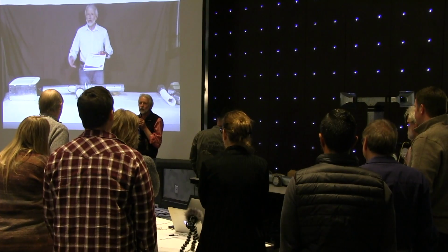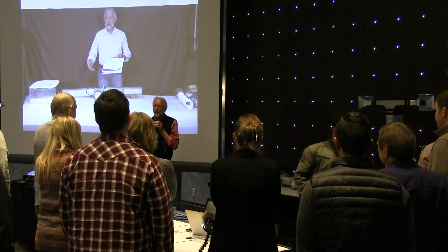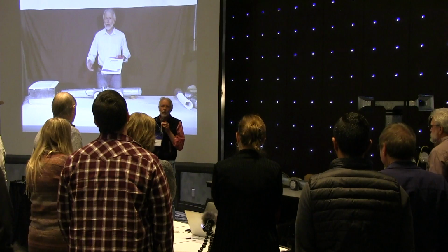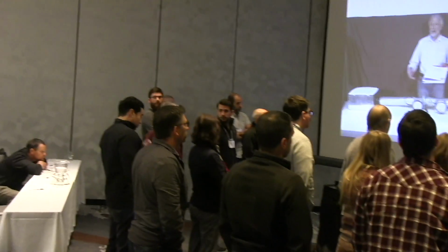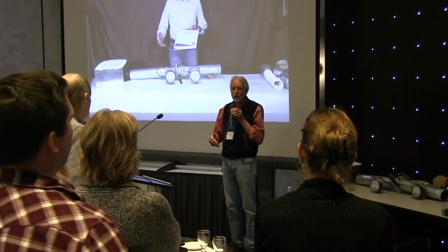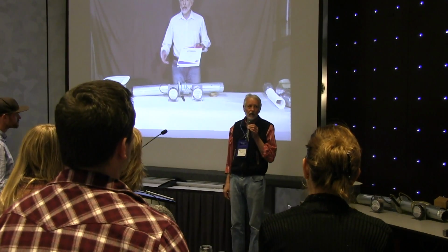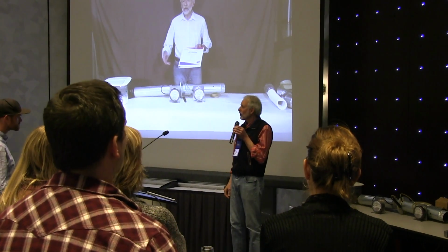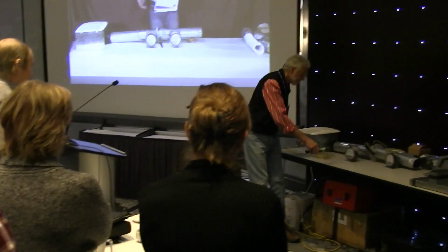So what we're going to do is show you two conditions that are very simple. What happens when I put my hand over the duct, which we have a special word for, it's called a shut-off condition. In the real world, that means if a bird builds its nest in your bath fan outlet, or the grill lids over, or in the case of a forced air heating system, if you pull out the air filter and it looks like a piece of cardboard, you have what are called shut-off conditions. So we can demonstrate that quite easily.